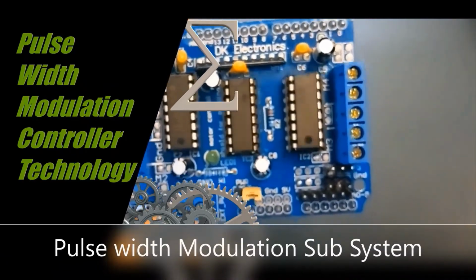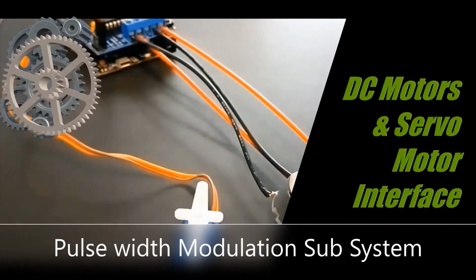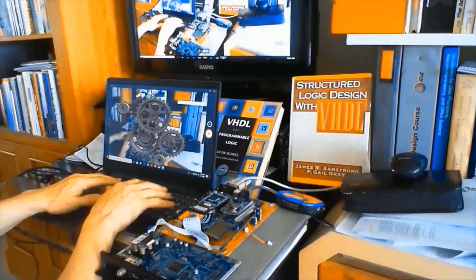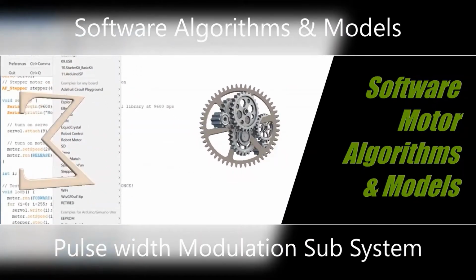The chip also handles all the motors and speed controls over I2C bus. 2 GPIO pins plus a 5-volt and ground are required to drive the multiple motors.